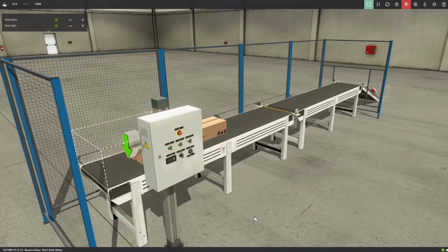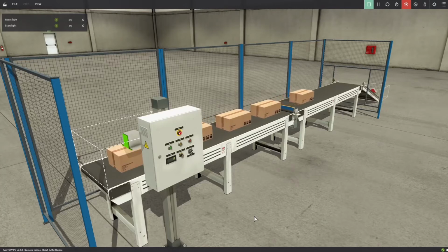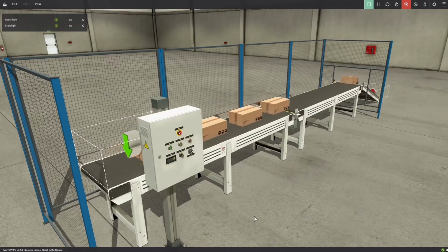The project takes place in a warehouse, in which boxes are being transported from one point to another by using two conveyor belts. The second conveyor belt only moves one box at a time, so when one box is on it, the first conveyor belt is stopped. As soon as the box has arrived at its destination, the first conveyor belt moves again and the process starts over. To prevent two boxes at the same time on the second conveyor belt, there is a divider in the middle that activates when the box enters the second conveyor belt and deactivates when it leaves.